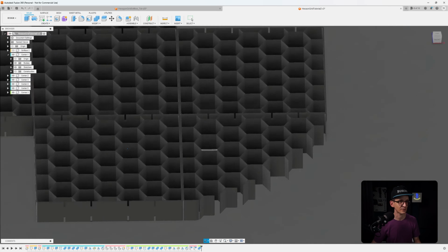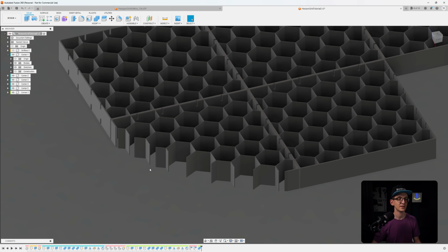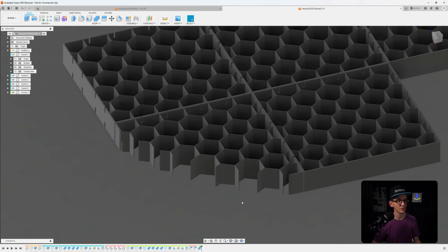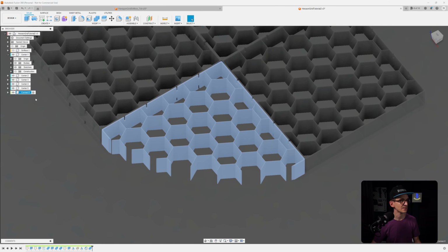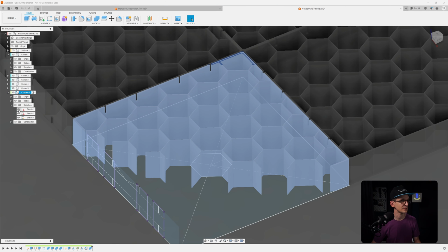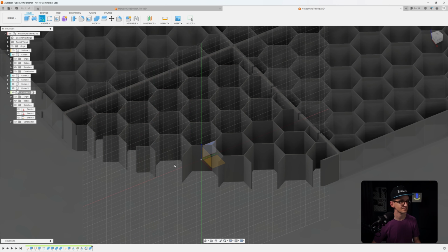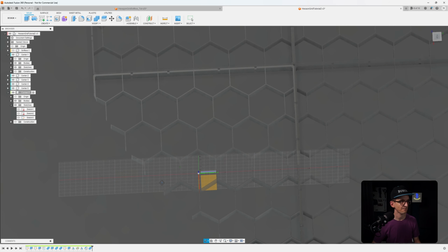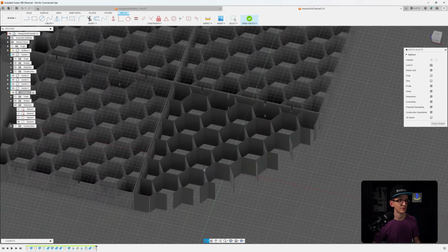So as you can see, we have now a corner piece that is following the shape of the softbox, exactly what we want, but the geometry is a bit broken here at the outside edge, which we still need to fix. So we go into the corner, select it as the component that we would like to edit, and then it is still featuring the original sketches, which is fine. And then we create a new sketch that is based on the bottom again.